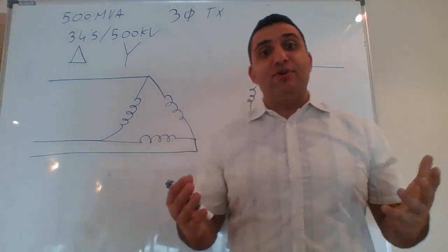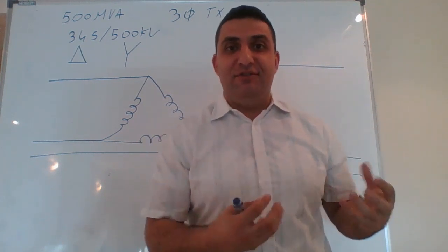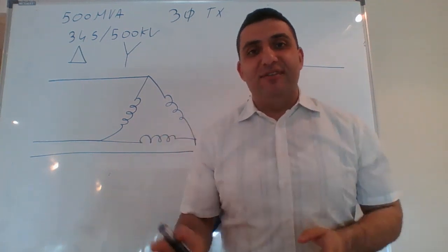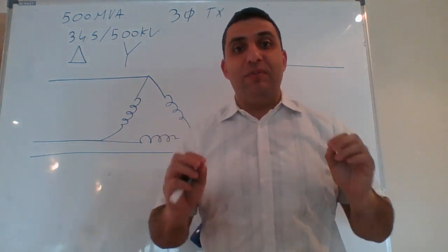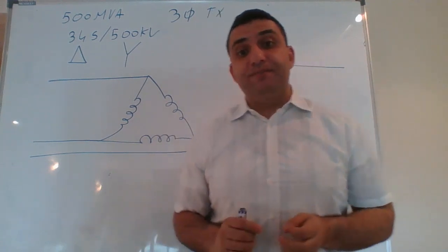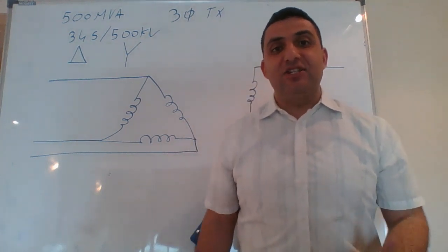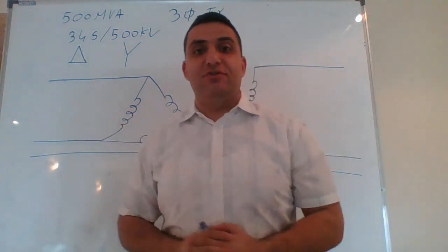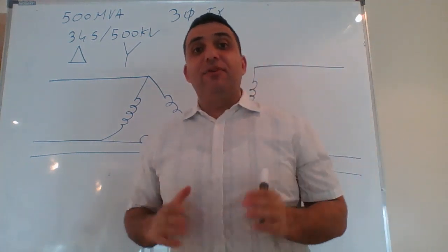That's why it is possible for us to design a harmonic restraint relay to avoid tripping our differential relay under inrush current, which would be a false trip. I wanted to clarify this point before we go into any discussion of three-phase differential protection. Now, let's start our three-phase protection.